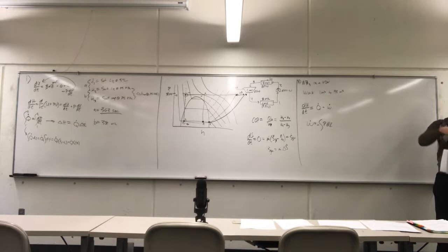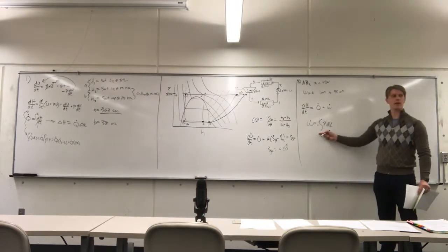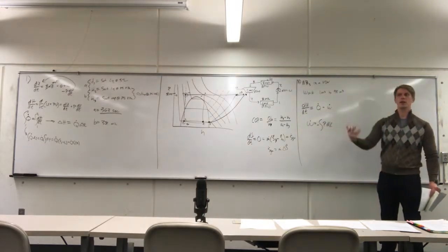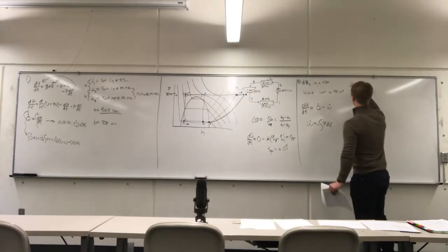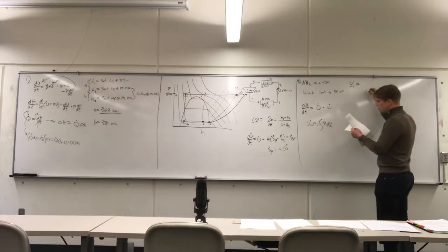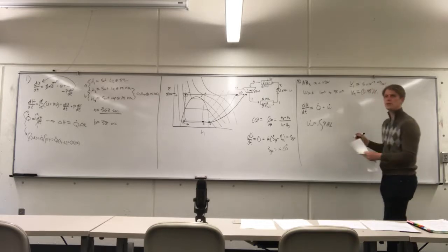So instead of having to calculate the big, long, complex delta U expression that we had in class, it was just a matter of integrating the van der Waals equation of state with respect to volume and then plugging in the two specific volumes. Specific volume 1 was provided. It was 5 times 10 to the minus 5 cubic meters per mole. Volume 2, if you did the math out, is effectively just 98% of V1.